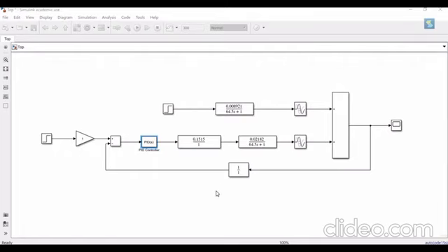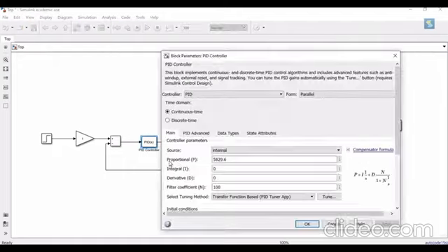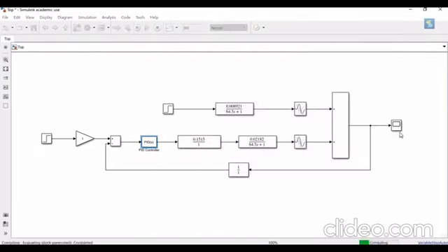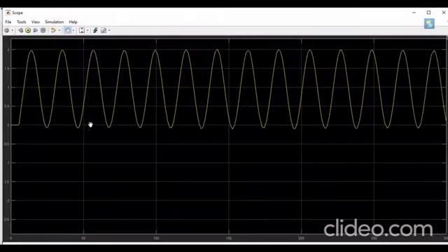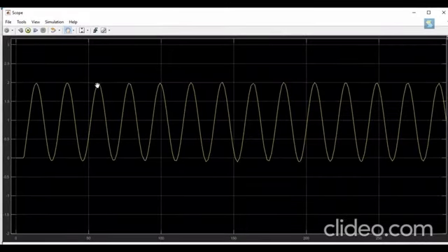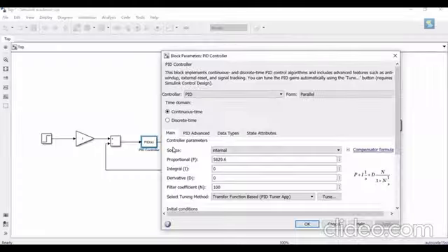So by using this method, first of all, we need to determine the value of Kcu, which is the ultimate gain, by using the trial and error of the PID controller. This one, by using a trial and error of the proportional. So when it's run, it will show until it shows the constant graph like this one, and then these 2 peaks, the distance between 2 peaks is taken as the Pu, which is the ultimate period, and the value of proportional P is taken as the Kcu.